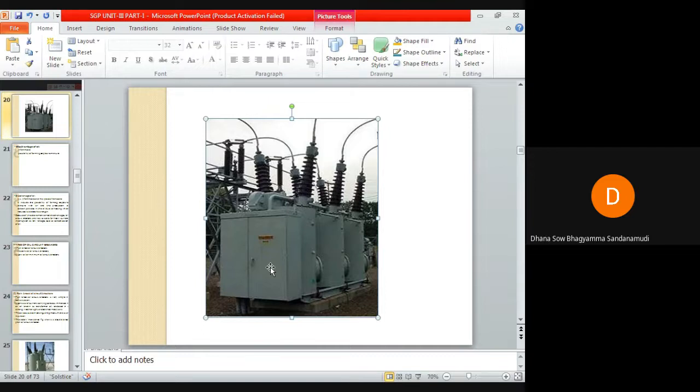In a circuit breaker, when an arc is struck between the contacts, the heat produced by the arc decomposes the oil into gases. Hence, arc energy is absorbed in decomposing the oil. These gases prevent restriking of the arc after the current reaches the zero point of the cycle.